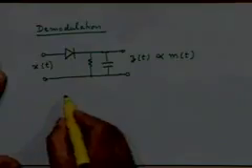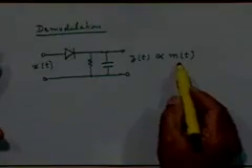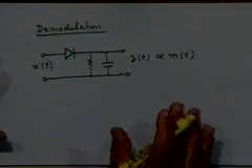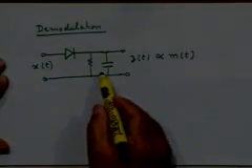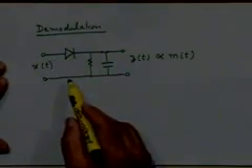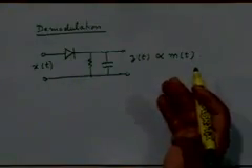Phase shift of pi by 2. m(t) is an arbitrary waveform. There is no concept of a phase shift of an arbitrary waveform. You can talk about delay of an arbitrary waveform. Unless it's a sinusoid, you can't talk about a phase shift. You can talk about a phase shift of a specific frequency component. So please remember, there is no concept of a phase shift. But in many cases, I do not know why you are mentioning that. I think you are mentioning that because you saw a capacitor there, right? No, you have to look at, remember, this is not a linear circuit. Do you see that? Isn't it? You can't just jump to any conclusion here. You have to see how this nonlinear circuit works for us to do what we want it to do. Right?